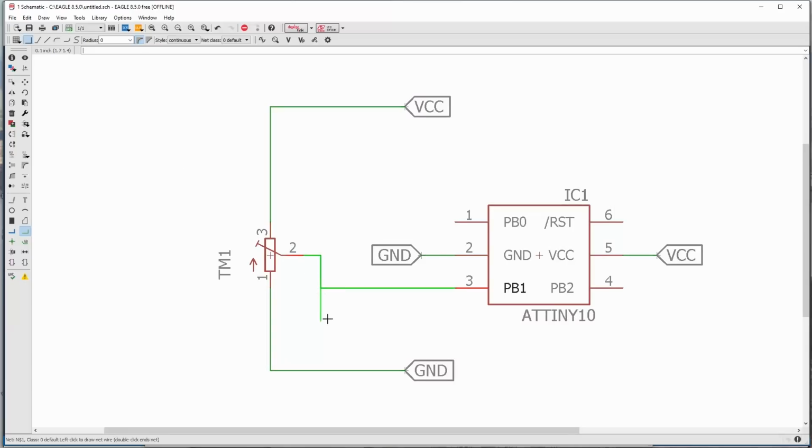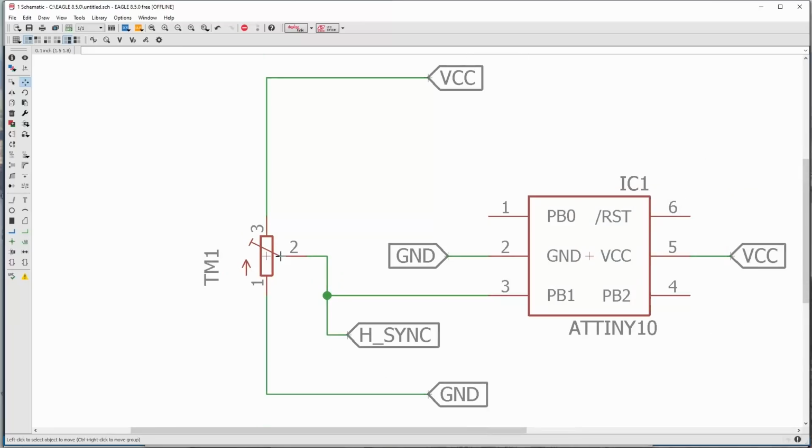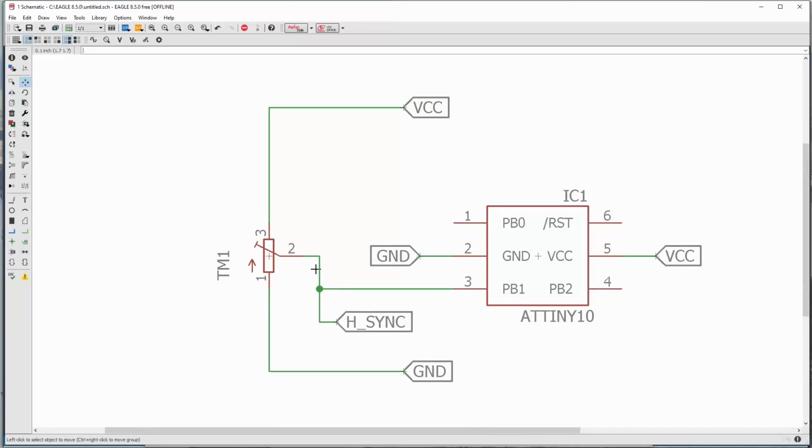However, there is one other thing that we need to think about, and that's that this is an open collector pin. Open collector is when you have a pin that you need a pull-up resistor for, because the pin by itself can only sink current and can't drive it. So if you have an open collector pin, you can't get 5 volts from it, but you can sink 5 volts. In this case, we have a voltage divider on it, so it will act as a pull-up. But I'm going to do a trick using the registers that will give us the same effect.